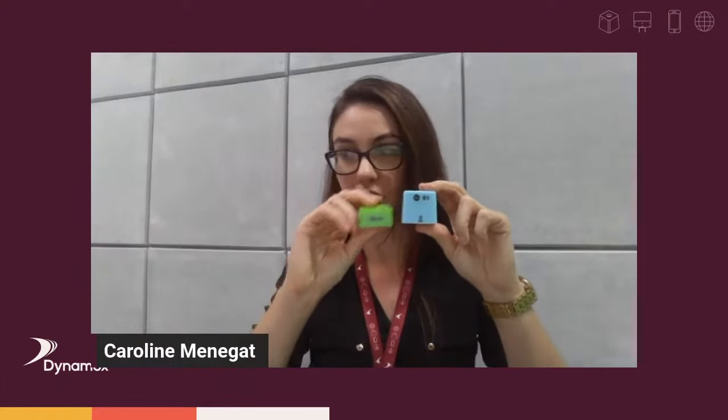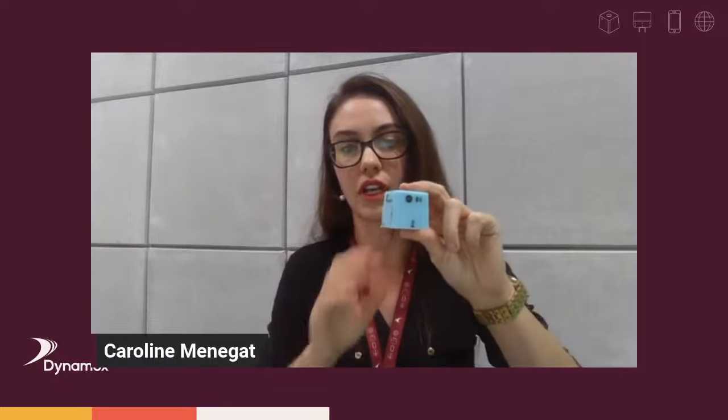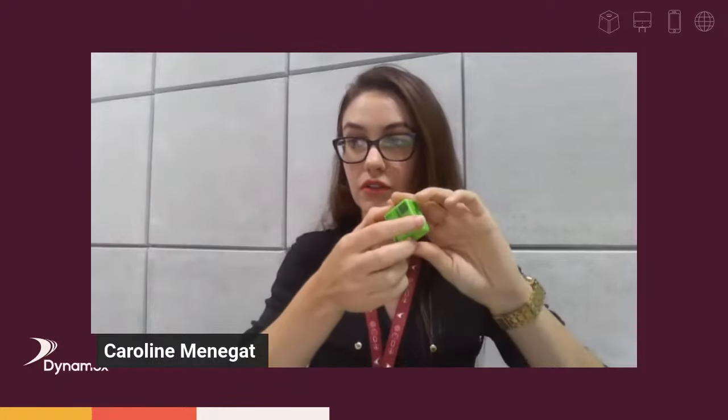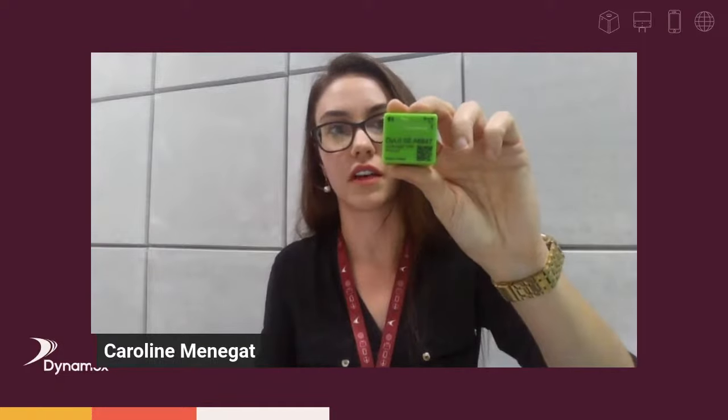All the sensors, as I mentioned, we do have different models here. This one is more recommended to monitor rotating parts such as motors, exciters. We are going to show some examples later. So this sensor collects data in terms of frequency, with a maximum frequency of up to 13 kilohertz. So that's the maximum frequency of this sensor. This other one goes up to 2.5 kilohertz. It also collects vibration measurements and temperature.